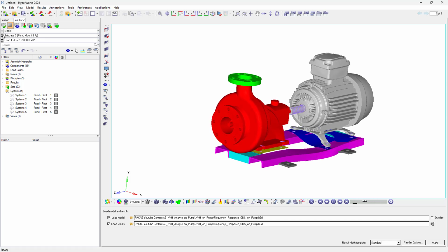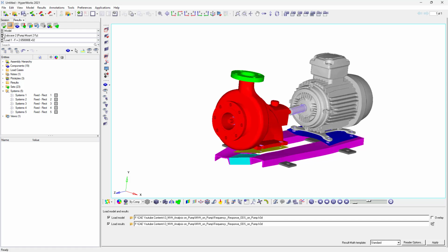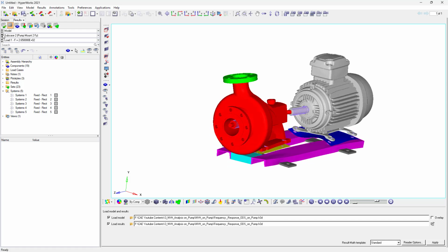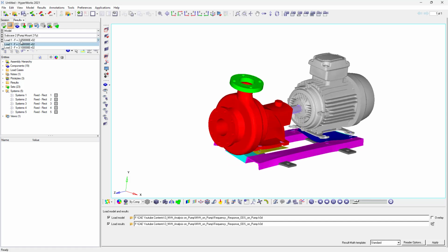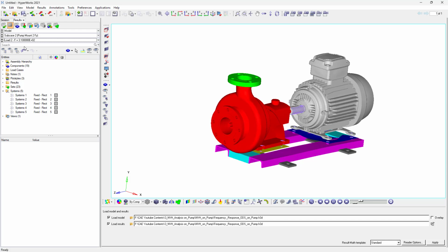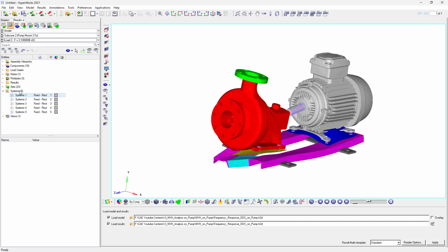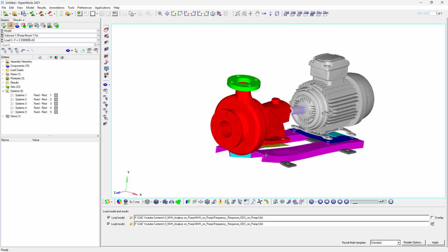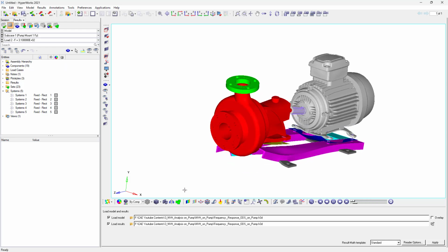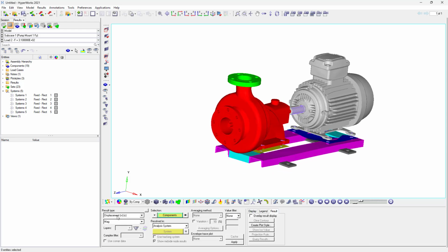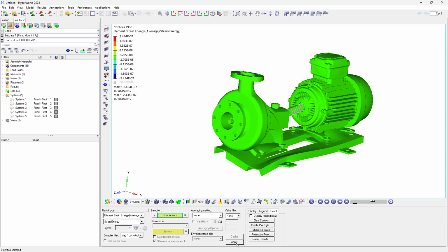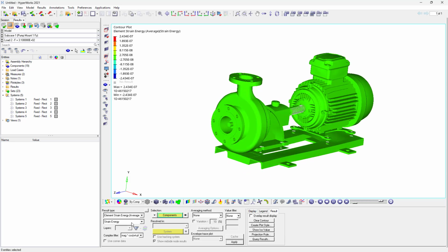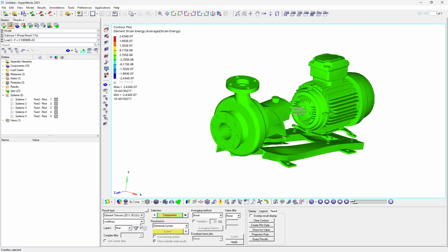Exactly the same, right? So if you consider mount 2, it should be 310 Hertz. So this was the critical one. At 265 Hertz, I don't see any impact on the mount. You could see that should be, I think, the first mount. And if I switch to the first one, you could see this is the third mount, and which is exactly doing the same.